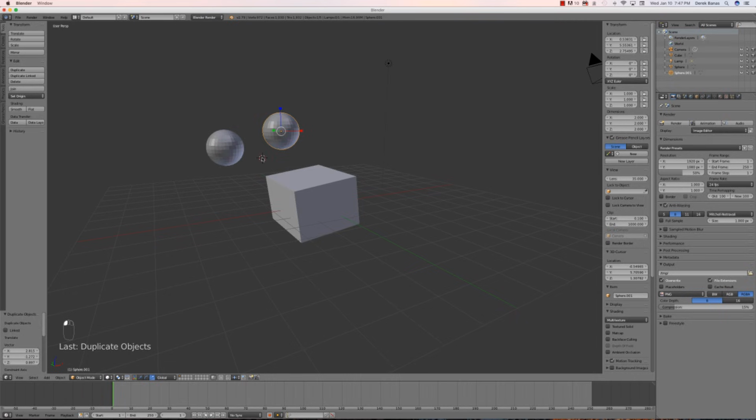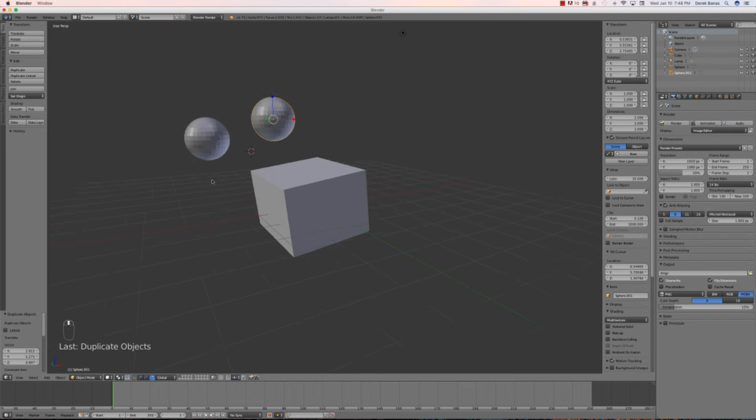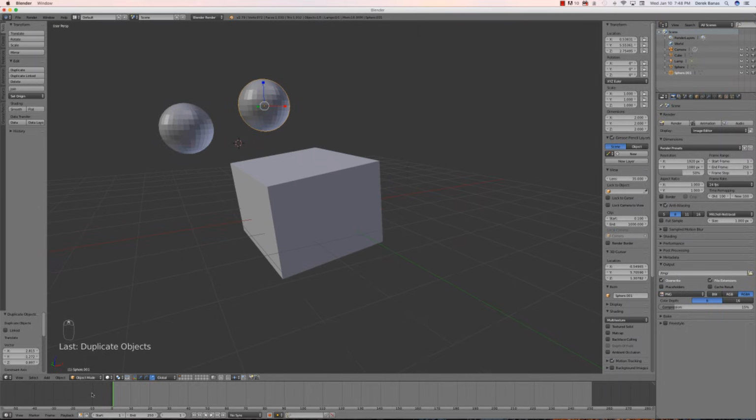Another thing that's very important to remember is if you ever do add new objects, always do it in the object mode, because if you do it over in the edit mode, objects that you are adding to your scene are going to be joined together. And I'm going to talk about how to disjoin objects in a moment, but I just wanted to mention that. We're also going to be able to view our objects in numerous different ways.